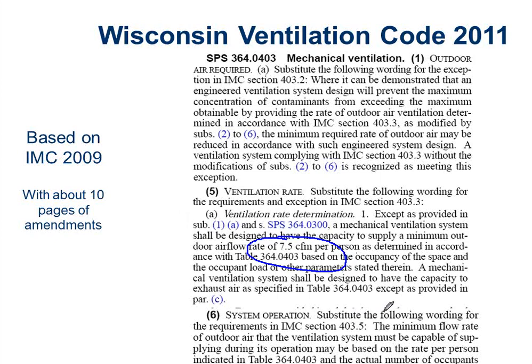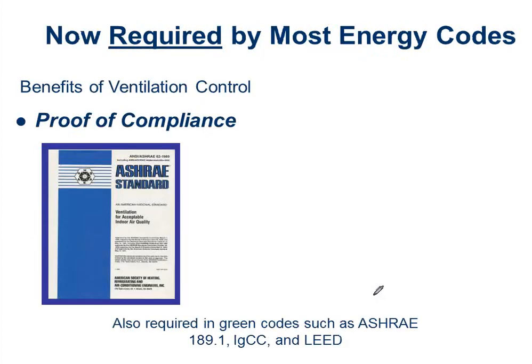And in places that are densely occupied, like movie theaters and gymnasiums and stuff like that, it makes a lot of sense. Other spaces like an office, it might not have the payback story in Wisconsin because the outside air rate's already much less. So not only is it allowed by all the mechanical codes, like I said, I can't think of one code that prohibits it.